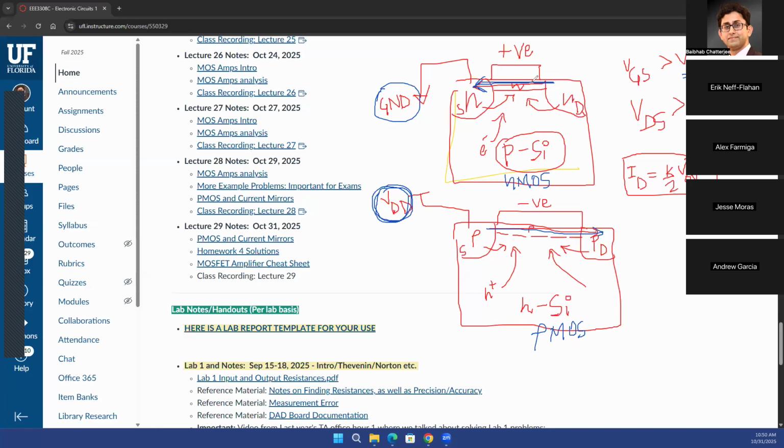So when we say a higher concentration of holes, it was probably, let's say, a particular number of holes per unit volume. And you want to have the same number of electrons per unit volume in the channel when you say that the channel has been formed. And that is another definition of the threshold voltage, coming from a device physics point of view.